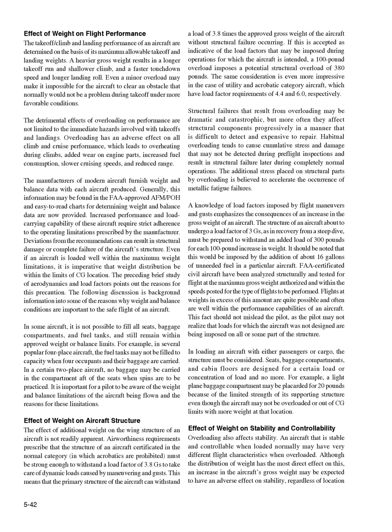A knowledge of load factors imposed by flight maneuvers and gusts emphasizes the consequences of an increase in the gross weight of an aircraft. The structure of an aircraft about to undergo a load factor of 3 Gs, as in recovery from a steep dive, must be prepared to withstand an added load of 300 pounds for each 100-pound increase in weight. It should be noted that this would be imposed by the addition of about 16 gallons of unneeded fuel in a particular aircraft.